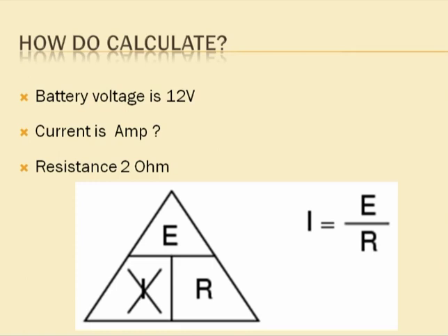Under the assumption that the temperature remains constant, we are applying Ohm's law. Second thing, you must know that Ohm's law is applicable both to AC circuits and DC circuits, but particularly in this chapter, we are confining our discussion to the DC circuit only. Now, the next two laws that we are going to discuss are known as Kirchhoff's laws.